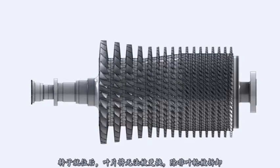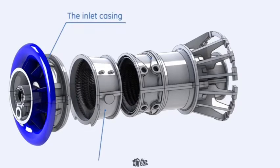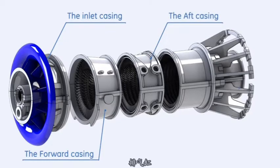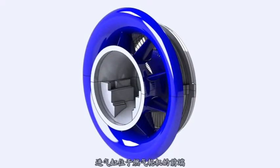Wheels must be disassembled. The compressor stator consists of 4 main components: the inlet casing, the forward casing, the aft casing, the discharge casing. The inlet casing is located at the forward end of the gas turbine.